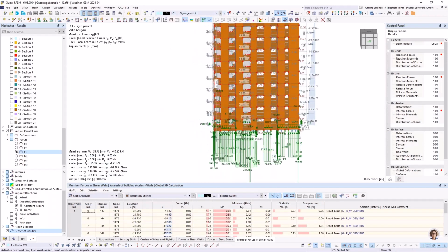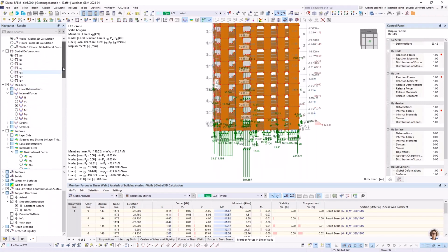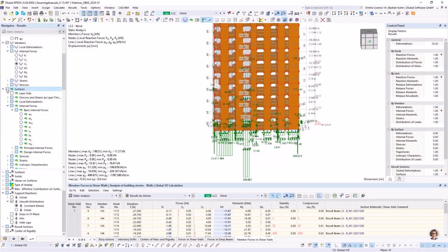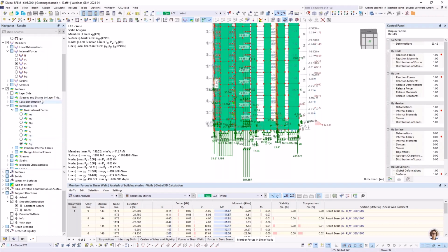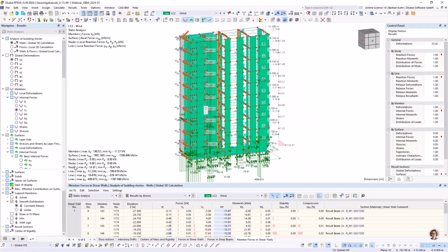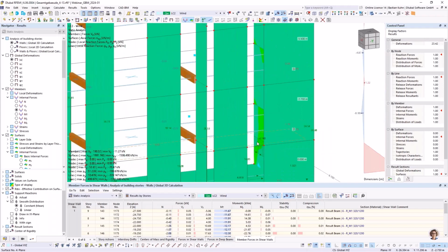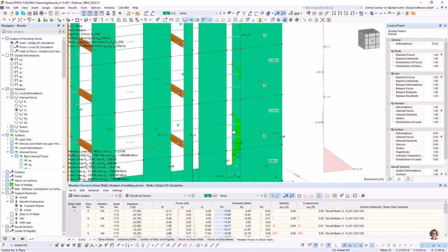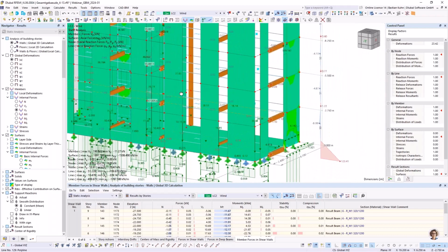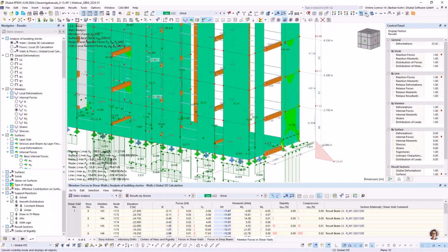Maybe if we go back to load case 2 again, for the wind, and we activate the shear force in the surfaces, and here in NXY, and now we are only looking at the walls, and we have quite a high NXY right here at this point. Maybe if we hold on, can I attach it? Yes, for sure I can. So here, and say visibility by these objects in here.